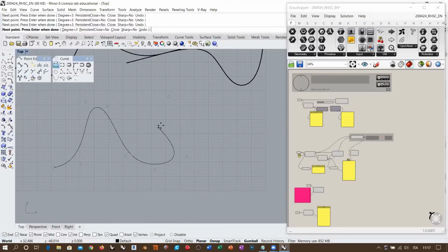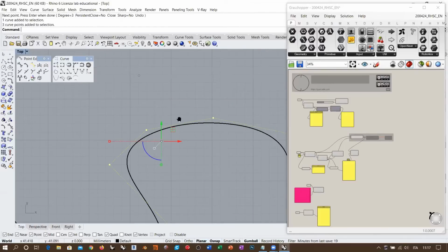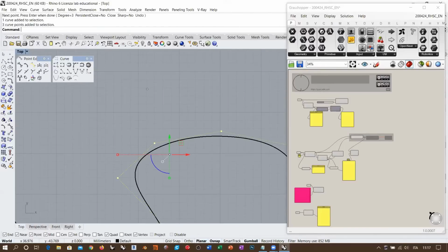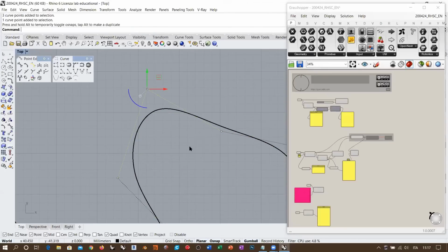So I always need 3 points that I can align, okay? And then I want this curve to do whatever it wants, okay? So I have these 3 points that I can use in order to define the passage through this one. So how can we proceed? Well, in this case, I will take the mid control point and place it exactly in the passage point, okay? And then I need to align these other two with this one.